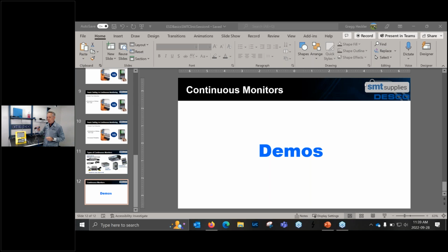So that's another one I'll show you. After I reinstall my snap, I have about 8 or 10 seconds before that audible signal kicks in again. So now I'm ready to go, and I would have, for instance, a real alarm now. Or if I take this out, and it's going to be annoying for a few seconds, if I rip my cord out of the thing, our monitors will also alarm for a short period to alert the employee that something happened, they're not grounded anymore, and then it will stop.